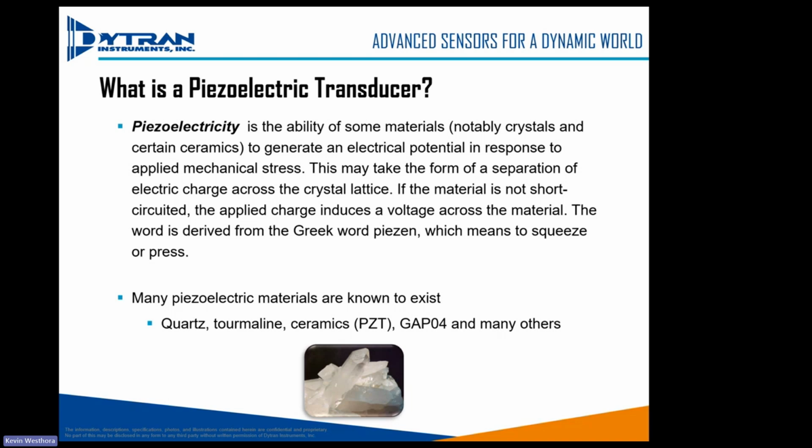So there's also a technology out there called piezo-resistive, a strain gauge. And we're all typically familiar with strain gauge technology. Piezo-resistive means changing the resistance in the wire to get a linear output to measure force or torque or pressure. In this industry, we're squeezing this crystal to get an electrical output.